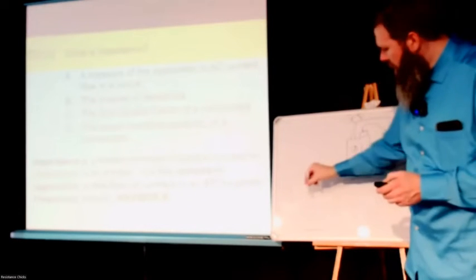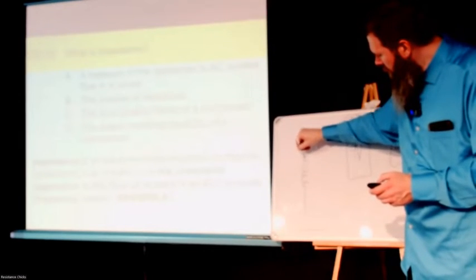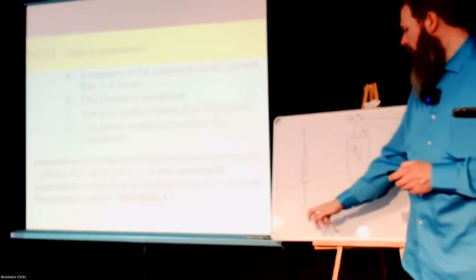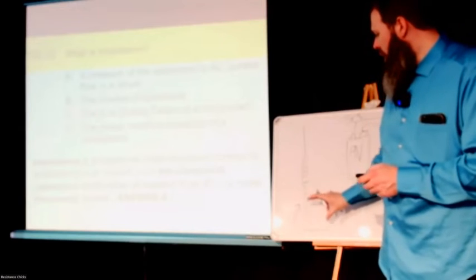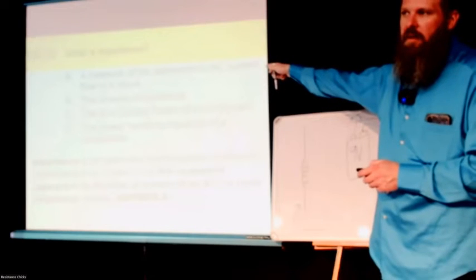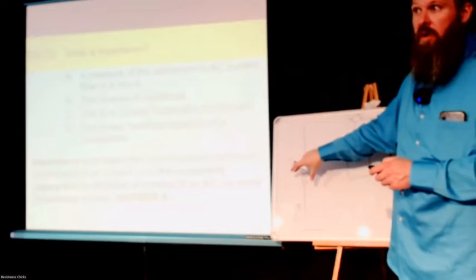Remember when I talked about that antenna, that dual band antenna, that coil? Your radio sends a signal here, and if it's on the proper frequency, it hits this coil, which opposes alternating current at a specific frequency based on the size of this coil.